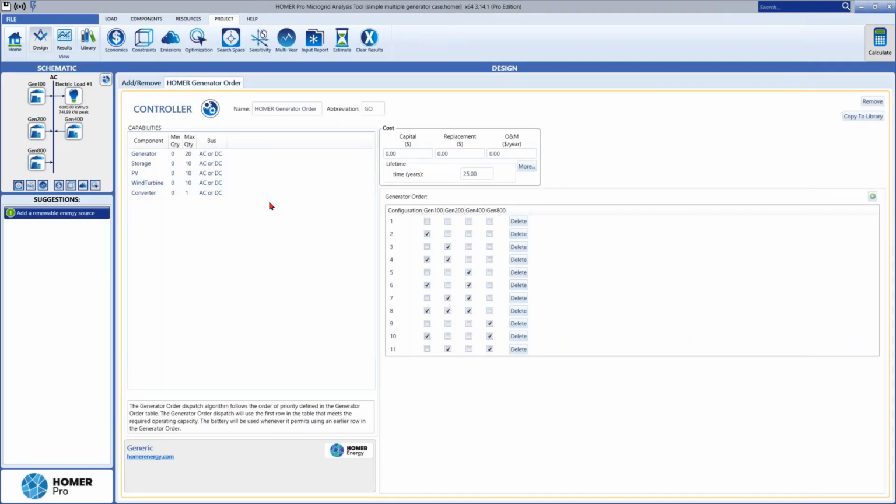Okay, so actually another one, and this relates to some of the updates we've made to HOMER Pro in all those major releases, and that is battery degradation over time. Talk about that in HOMER. Well, we have three different battery models. An ideal model, which is just super simple, it's just the ideal battery. So if you have no data at all, but it's overly optimistic, really. We have the original kinetic battery model that originally came out of University of Massachusetts. NREL's been using it for a long time, and that's the most common one we use.